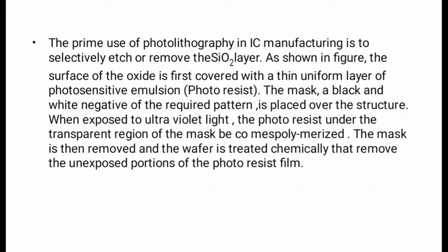The mask, a black and white negative of the required pattern, is placed over the structure. When exposed to ultraviolet light, the photoresist under the transparent region of the mask becomes polymerized. The mask is then removed and the wafer is treated chemically to remove the unexposed portion of the photoresist film.